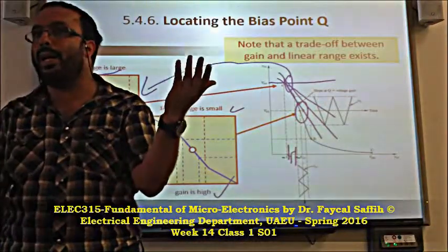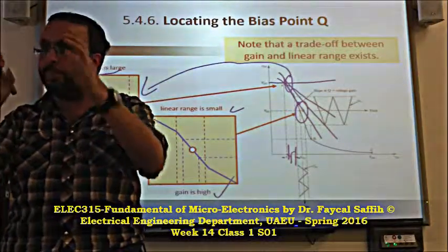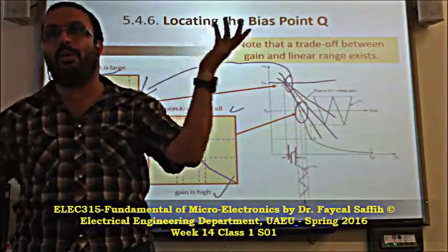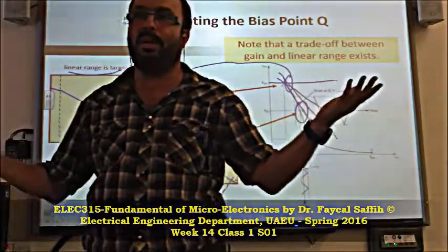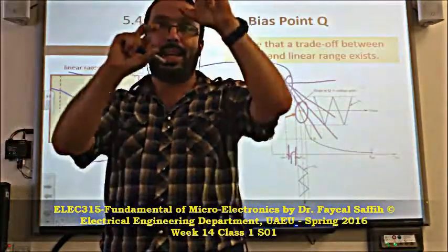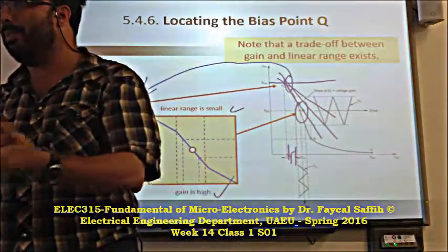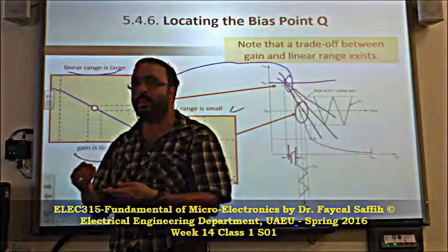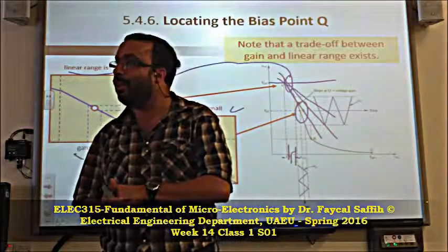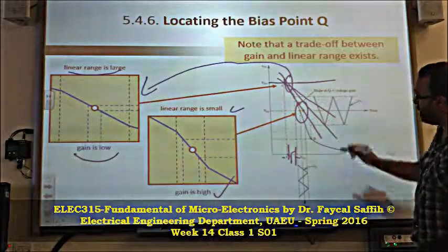There is no linear relationship. Because if they have the same linearity, it means the amplification will have the same factor for this guy and this guy. When I divide, the amplification cancels out and the ratio will be the same. Means the picture stays the same. Now if it's non-linear, the ratio between them will not be the same ratio as before the amplification, which is bad. That means I distorted. Distorted means I twisted the information. I don't have accurate information of my reality, of my signal. So that's the bad news.